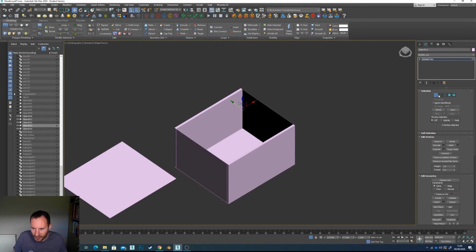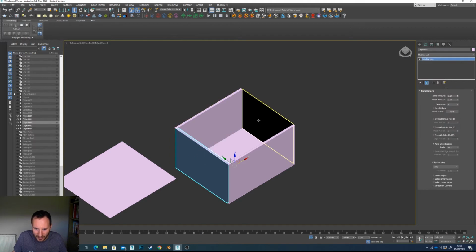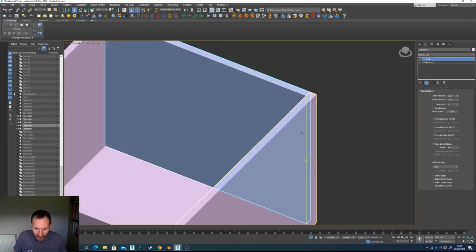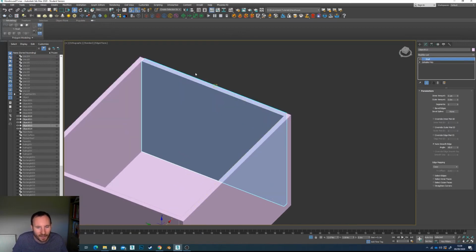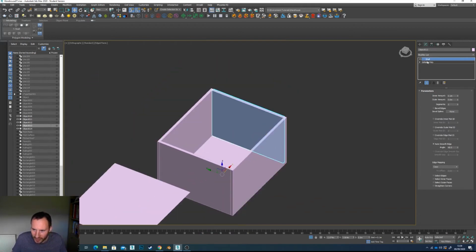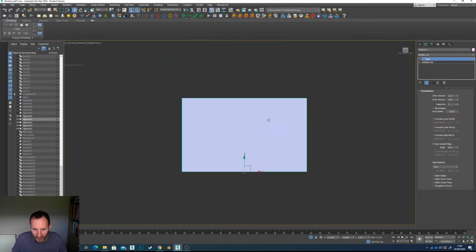And then what we can do is, now we've done that, we'll just paste the shell on top. And we'll do that again here. So we now have our thickness of our walls in our office. So they're not particularly thick, certainly not as thick as external walls, but that's what you'd expect. I think what I've done is actually probably slightly thicker again, but we can always inset parts and add thickness elsewhere. So what I'll do now is I will just go for the front view, make sure I've got that front wall selected, or you make sure you do.